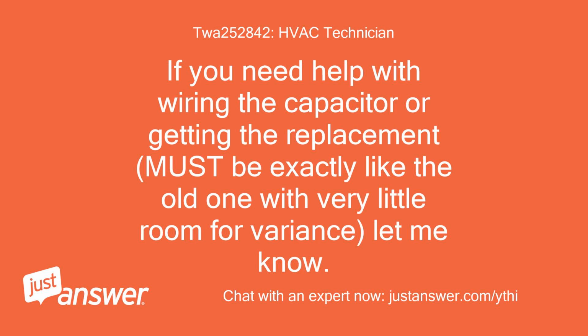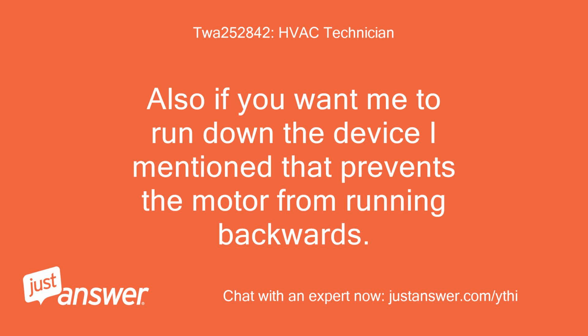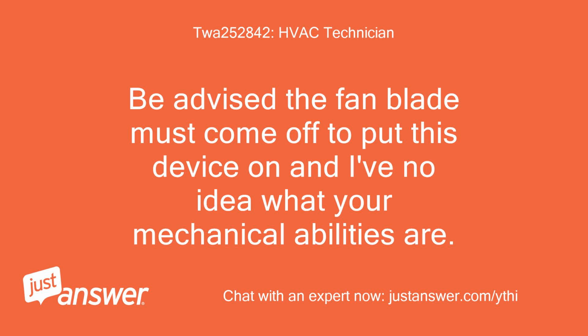If you need help with wiring the capacitor or getting the replacement, which must be exactly like the old one with very little room for variance, let me know. Also, if you want me to run down the device I mentioned that prevents the motor from running backwards. Be advised the fan blade must come off to put this device on, and I've no idea what your mechanical abilities are.